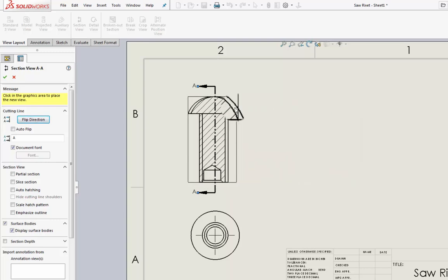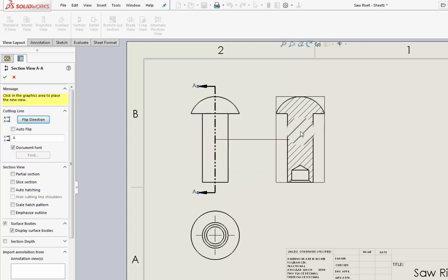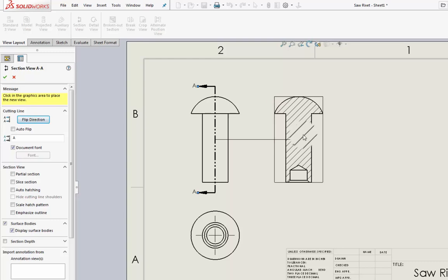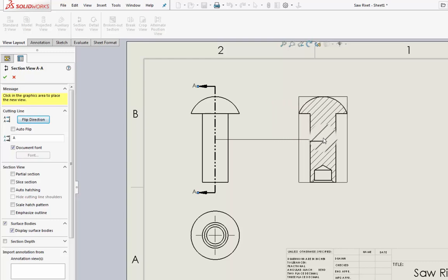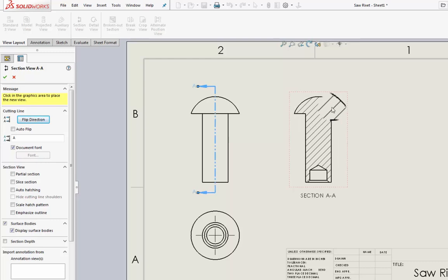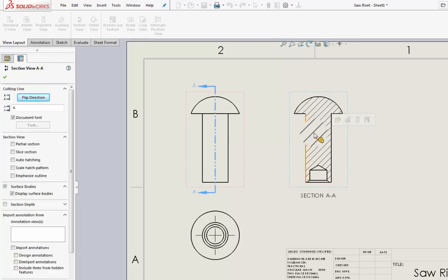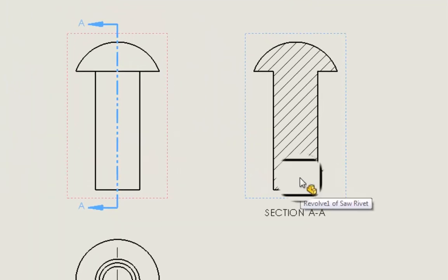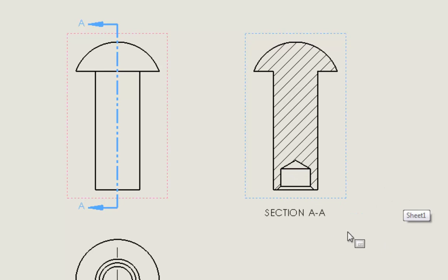So that's like cutting this view right down where those dotted lines are. And then what does it look like when you slice it right in half? Well, this is what it looks like when you slice it right in half. So the hatch marks here are where it's flat, as if you had cut it. And notice down here, this is the hole. Now it has solid lines because we cut it open and you can see it very clearly. That's the whole purpose of the section.